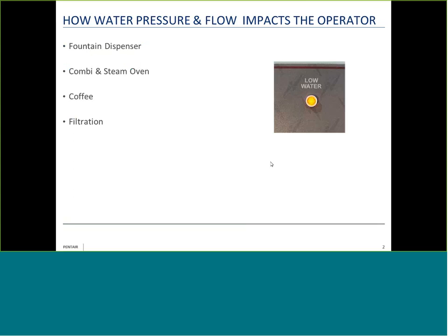You've all had that experience of someone flushing a toilet in a building while you're taking a shower and you suddenly get hit with hot water. That's not because the hot water is getting hotter. That's because the pressure has dropped in the rest of the system on the cold water side, that it's dropped that flow throughout the building. So you get a shot of hot water.